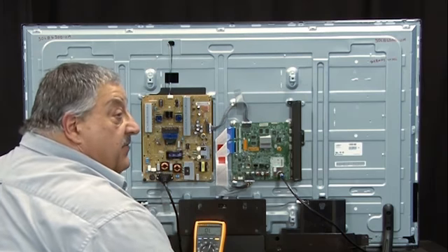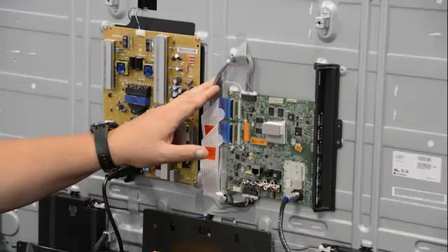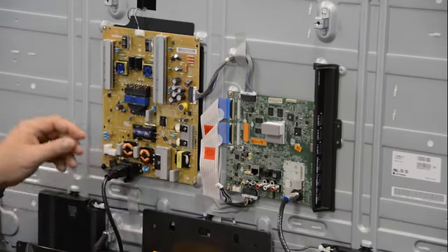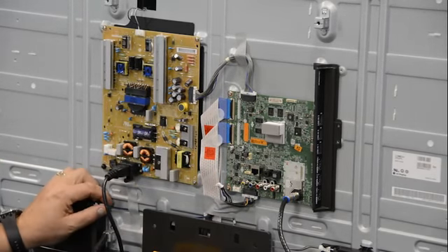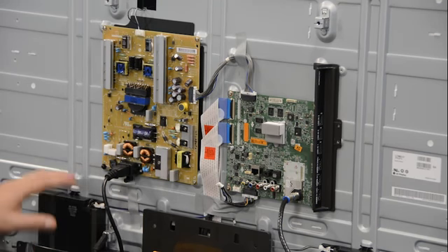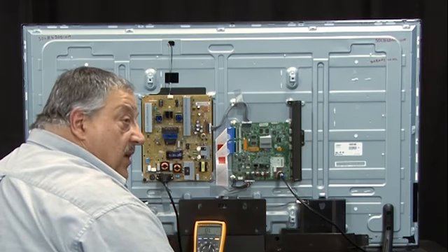So this is the way you're going to find out one thing or another, okay? You're either missing power, you have an open connection or unseated connector, or you have an open or unseated connector on the speaker side, or you have open speakers. And you can isolate it and walk it down to that specific major component.